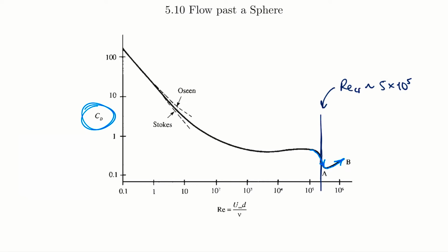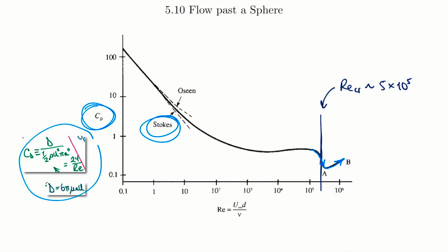We're also showing on this plot the Stokes flow, which is what we solved for before, creeping flow around a sphere. And so I included those equations here so we could see this was the drag right here. And then our C_D, our dimensionless drag coefficient, we got that it was 24 over Reynolds. And that's what we're seeing with this dashed line right there on this plot.